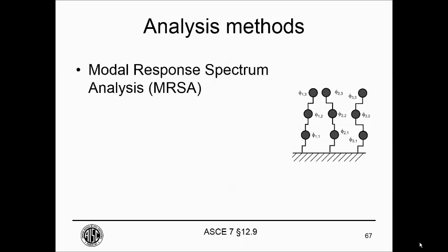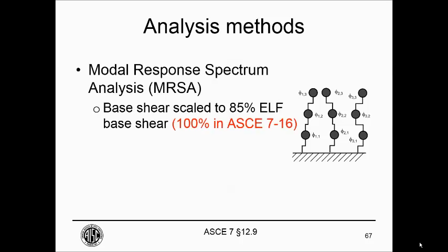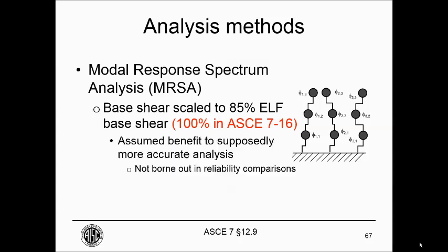The modal response spectrum analysis is scaled to the equivalent lateral force procedure base shear. In 2010, the scaling factor is 85%. In 2016, that scaling factor is 100%. The code committees have long assumed that the modal response spectrum analysis has some sort of benefit in terms of better proportioning.